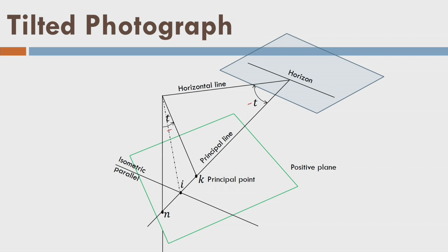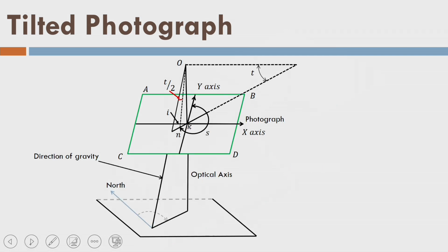So, now we are trying to find out I also, right, and there is a reason for that, we will see how. So, this isocenter is there. Now, we have understood what is a tilted photograph. So, in the books you will find this kind of photograph, where this is my end point and this is my K point, and this is the total tilt angle. As a result this point is my isocenter, which is the bisector. If I bisect that tilt angle, I will get the point I, the isocenter on the image.